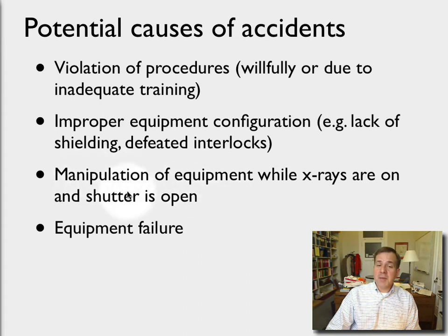I will say that sometimes this is necessary. For instance, in particular cases when we're aligning X-ray diffraction equipment, we need to manipulate certain parts of the equipment while the X-rays are on and the shutter is open. And this of course requires extreme caution, and it should never be done without the permission and probably the presence of the principal investigator responsible for the lab. In the case of the X-ray diffraction equipment in our building in materials science, that's me. If anyone was ever trying to align equipment, I would certainly want to know that and probably be there while it was going on, because you have to be very, very careful when you're doing that.